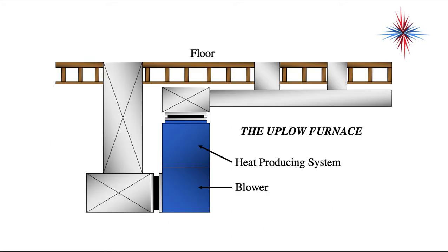So this is an upflow furnace. So we have our return ducts here. In this case, it's coming in from the side. And then the air blows through the blower compartment, gets sucked in, blows through the heat exchanger, and comes out the supply plenum to the registers.